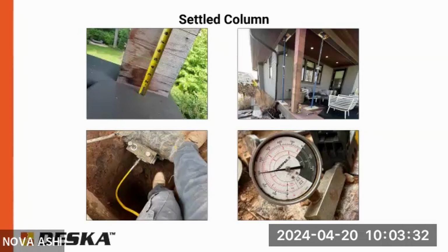Well, the failure mode would be the corrosion, but that's basically how long it would take for the steel to corrode enough that there wouldn't be enough section there to support the load above. And since most piers are installed with at least a safety factor of 2, how long would it take a hot dip galvanized steel member in the ground to lose, say, half of its section? Yeah, lose half of its section.